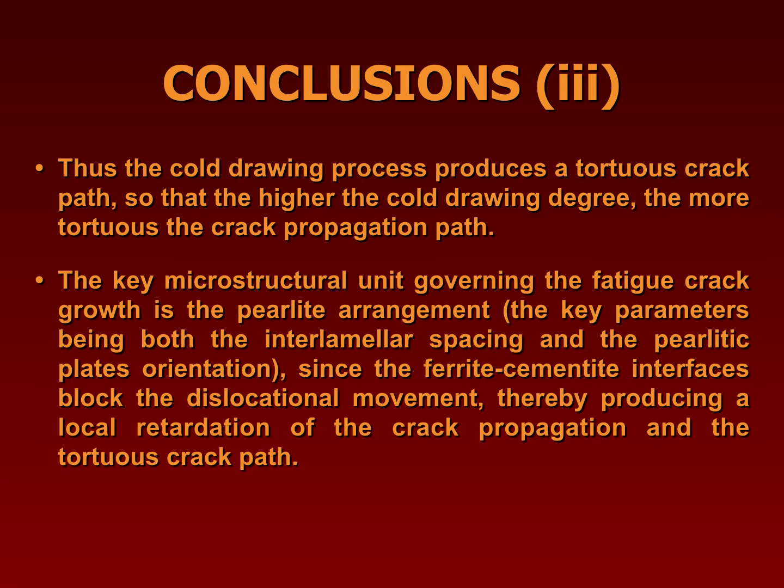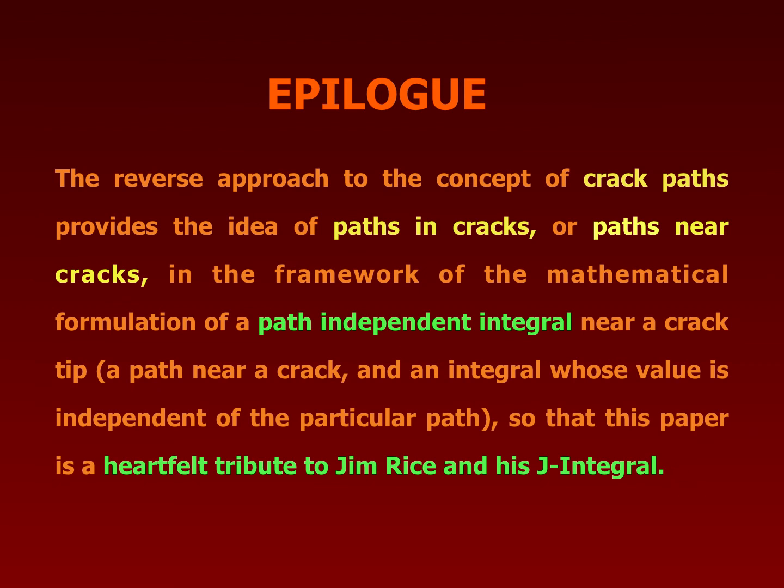The key microstructural unit governing the fatigue crack growth is the pearlite arrangement, the key parameters being both the interlamellar spacing and the pearlitic plates orientation, since the ferrite-cementite interfaces block the dislocational movement, thereby producing a local retardation of the crack propagation and the tortuous crack path.